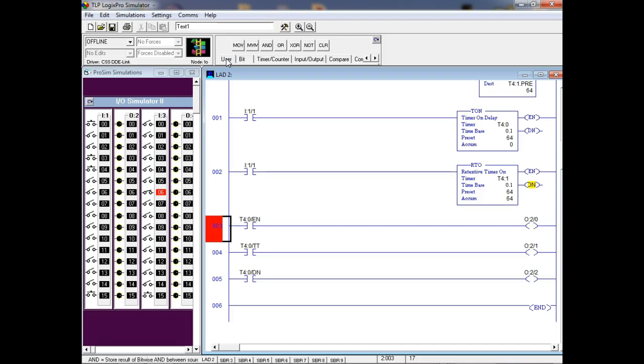So I stop my line, I make a correction. Well, with a non-retentive timer, what did I just do? I lost my time. My retentive timer, I kept it. And then I could use the timer done to reset it, because it's only going to become true after 64. But what I could do is keep stopping it. You understand what I'm saying?